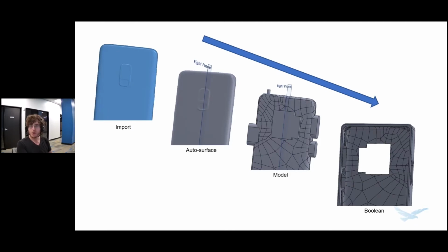So just a quick rundown of the overall process. We input our mesh. This is from the top left, and then we convert it into a solid with that auto surface. So as you can see, we now have this kind of gray body. This is solid information instead of just graphical information. I went about modeling button locations. So, where my camera is, where my power button and the volume button are, I want those outlined so I can create this reference body.